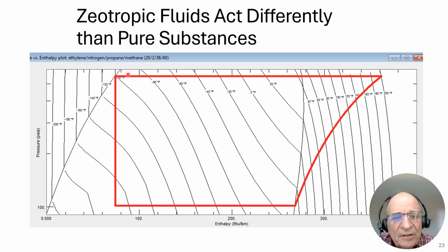What was my pressure up here? Remember, this is a logarithmic scale. So this is 100, 200, 300, 400. This started off at, looks like about 550 psi absolute. And where did it end up? 100 psi absolute. Now, what's in here? Is this the fluid that's in here? Not really. It's really the fluid that's here and the vapor that's here. So this is an alphabet soup of what is actually in here because it's both liquid and vapor, and it's at different compositions. And the liquid and the vapor are at different compositions as well.